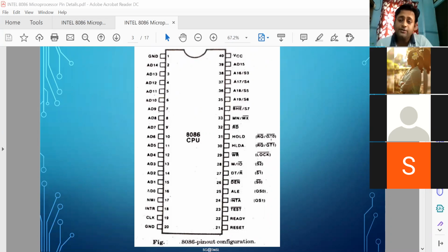Yes, fetching can be stopped, but the execution never stops, so the queue is always decreasing its space. When the upper 2 byte space is empty, the fetch goes on. When the lower queue position is empty because it is ready for execution, at that time an 8 bit position is empty.